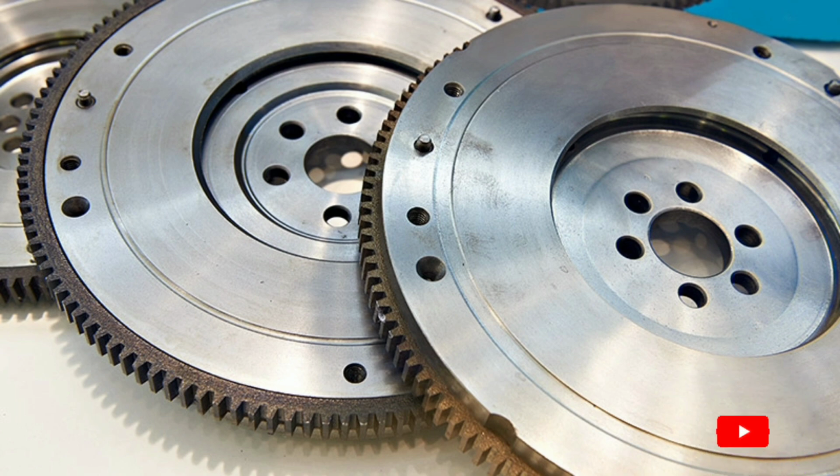What you have to keep in mind is that a flywheel has two purposes. The first purpose is that it is used as an aid in the starting system during starting. It also transfers the engine torque produced during the combustion or power stroke to the transmission system until it is delivered to the driving wheels, and it dampens the torsional vibration and prevents it from being transmitted to the transmission system of the motor vehicle.